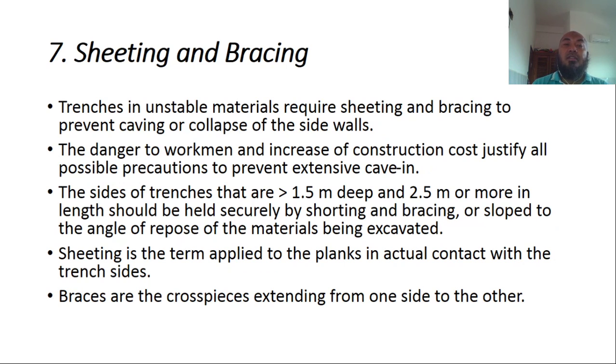Okay, sheeting and bracing. Trenches in unstable material require sheeting and bracing to prevent caving or collapse of the side wall. The danger to workmen and increase of construction costs justify all possible precaution to prevent extensive caving.